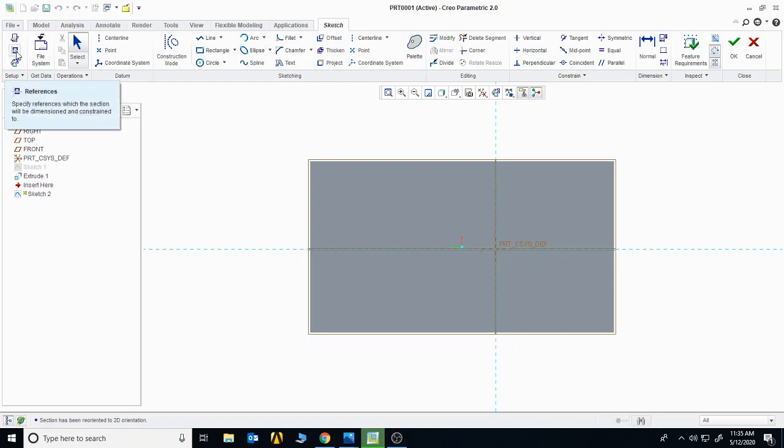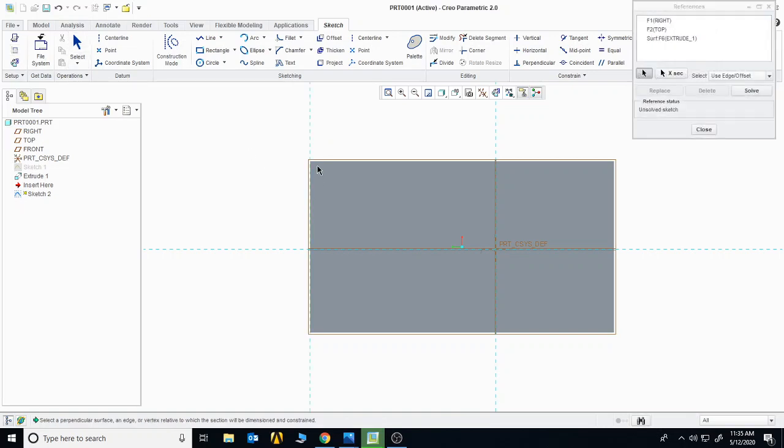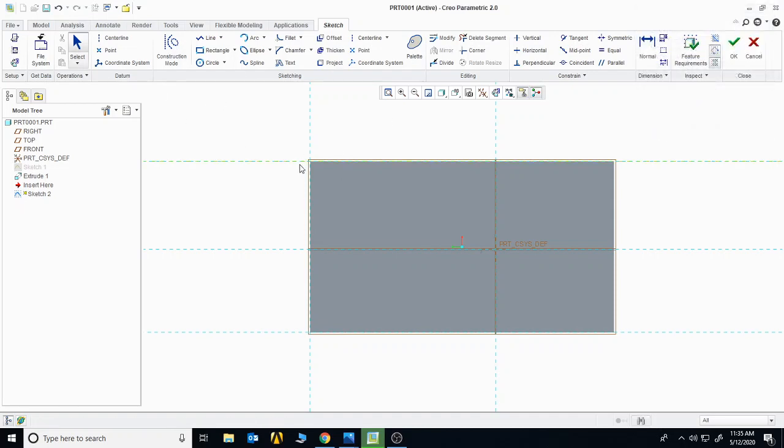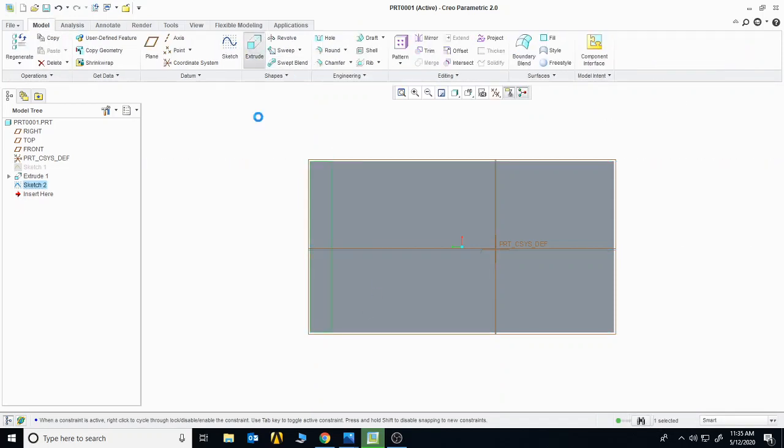You can see references here. These references are used to easily let you know the starting and the ending point of the last entity. If I want to draw a rectangle here directly, it's not possible for me to accurately guess the starting point of the previous rectangle. So for that we can use the references. Click on the references, click on the sides, and you can see the dotted lines appearing. Once they appear, you can now easily guess the starting point of the previous entity. Again, click on the rectangle, click on here and on here. Okay, extrude it.